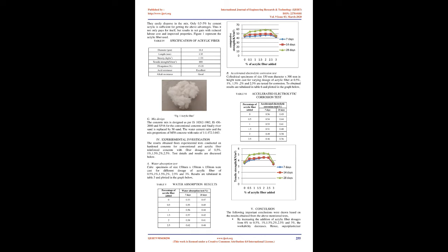F. Acrylic fiber. Acrylic fibers are synthetic fibers made from a polymer, polyacrylonitrile, with an average molecular weight of about 100,000, or about 1900 monomer units. For a fiber to be called acrylic in the United States, the polymer must contain at least 85% acrylonitrile monomer. DuPont created the first acrylic fibers in 1941 and trademarked them under the name Orlon. Strong and warm, acrylic fiber is often used for sweaters and tracksuits and as linings for boots and gloves, as well as in furnishing fabrics and carpets.